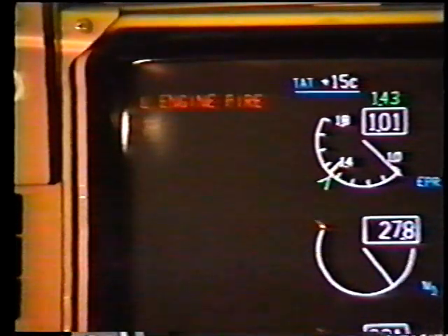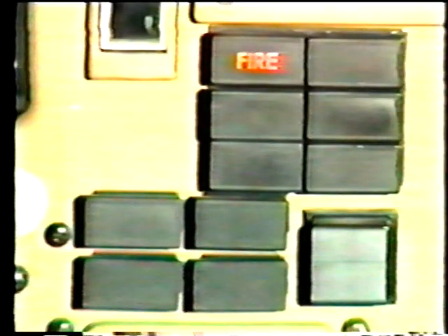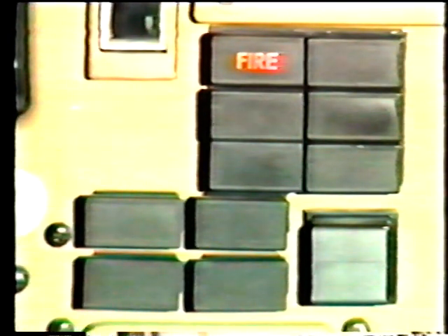The crew is alerted visually to a warning by a red ICAS message, master warning lights, discrete annunciator warning lights, and for fires, specific system indications. All warning alerts include a bell for fires and a siren for all other warnings except the ground proximity warning system.